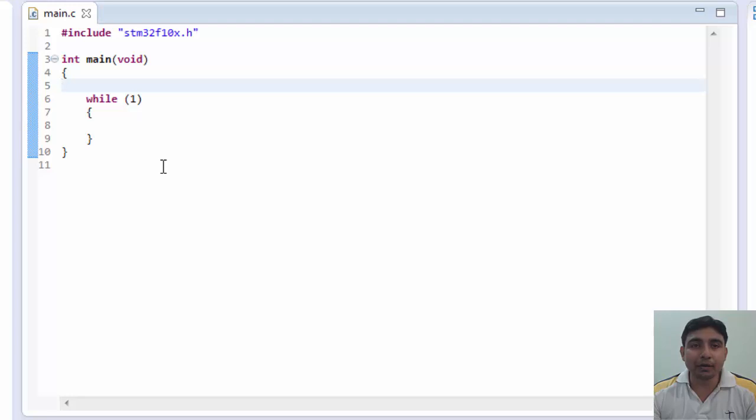If you remember, when we created new project for STM32F4 Discovery board, we changed the clock settings. But for this STM32VL Discovery, Atollic TrueSTUDIO by default gives us the correct clock settings. So we don't need to update any clock settings now. Okay, so now our project is created.